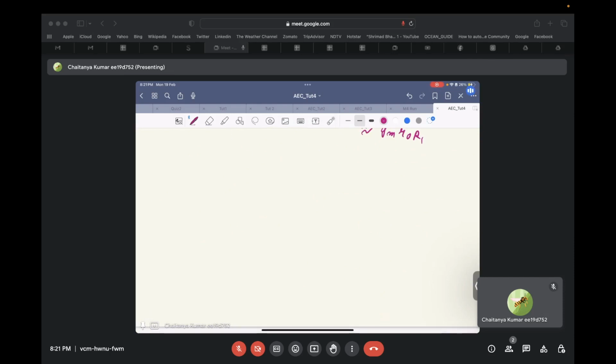So we know, as we have discussed till now, that if a controlled source has infinite gain and it is present in negative feedback, then the controlling parameter of that particular controlled source will go to zero. So, with this concept, we'll try to analyze a few circuits and try to verify this concept on them.